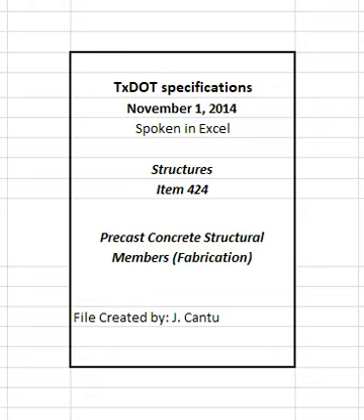4.2.5.3.2 External vibration. 4.2.5.3.2.1 Form vibrators. Form vibrators may be used to consolidate thin members, supplement internal vibration, or consolidate members with highly congested reinforcing steel. Determine the size, number, and location of external vibrators to provide enough intensity of vibration to the desired area of the form. Adjust the spacing, frequency, amplitude, and duration of vibration according to the concrete mix and size of member to produce uniform consolidation of the concrete.